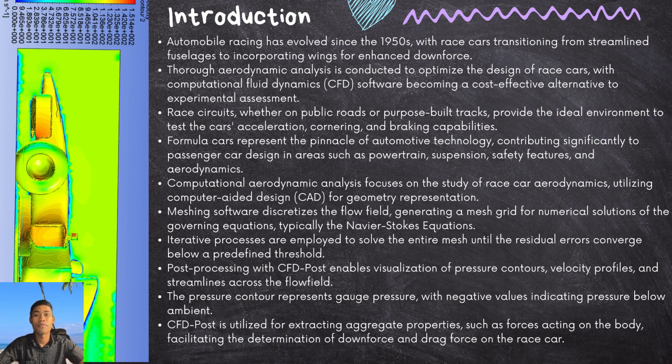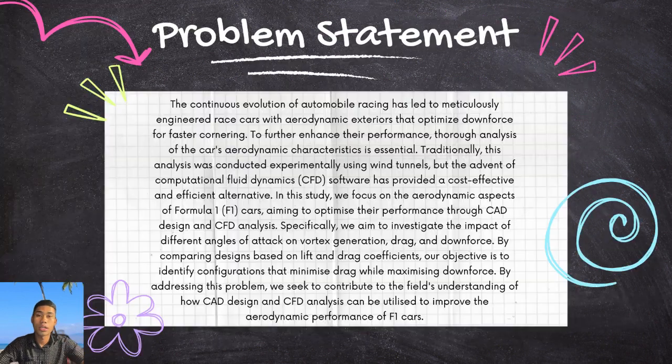For post-processing, CFD-Post provides visualization of pressure contours, velocity profiles and streamlines. Negative values in the pressure contours indicate pressure below the ambient level. CFD-Post also extracts the aggregate properties determining the downforce and drag force exerted on the race car. Next we will move to the problem statement.